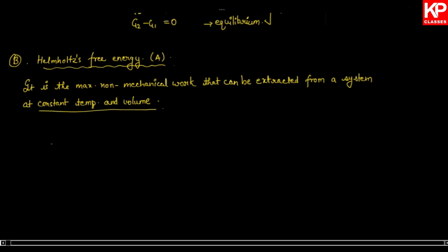Similarly, based upon the first law, we are going to derive this relation. We know that del Q minus del W total gives dU, that is the change in the internal energy, right? So you can write del W total will be equal to del Q minus dU.